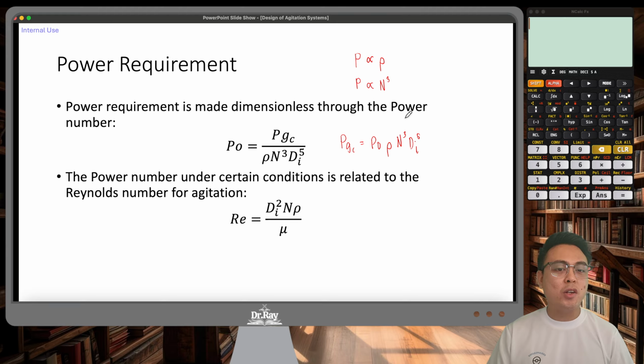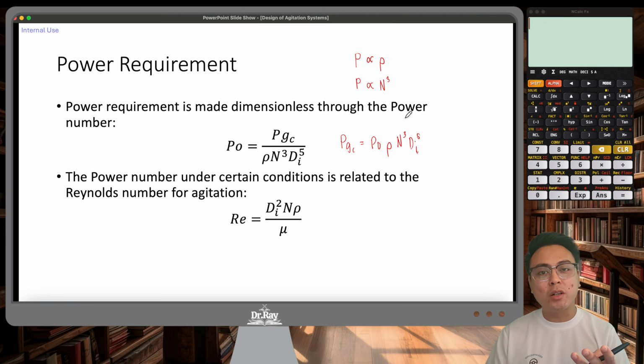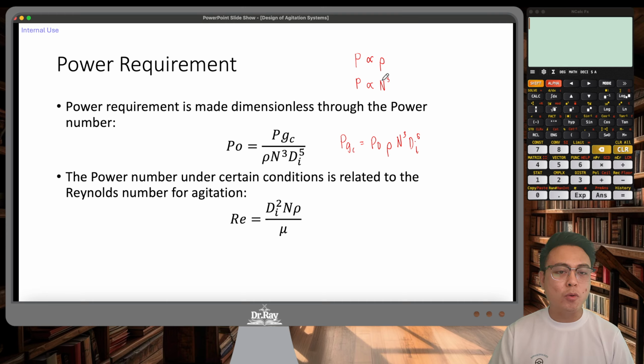For an electric fan, you have different speed settings, and if you turn up the speed to the highest setting, just know that you are consuming the most power for that fan. So for agitators, power is directly proportional to the cube of impeller speed. So impeller speed has a big impact on the power consumed.